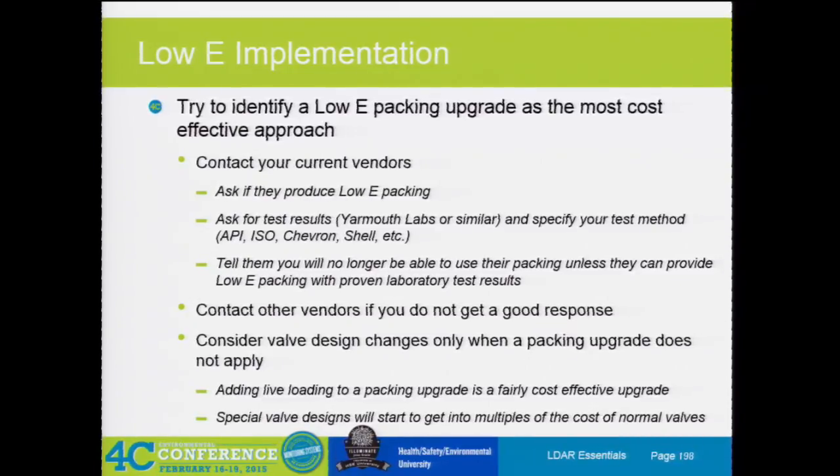Consider valve design changes only when packing upgrades do not apply. So what we're saying here is it's a heck of a lot easier to replace a packing set, replace your packing gland, than buying a whole new valve. So if you can fix it with just packing, I would recommend doing that, where packing's like $5, where buying